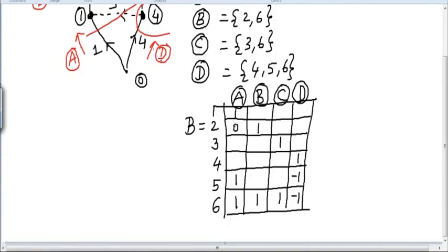Rest all the things are to be filled by 0. So in this way, basic cut set incidence matrix also is calculated. After this, let us partition it, because unless and until we make a partition, we will not be able to prove the fourth identity, fourth bit that is to be proved, that is CB is equal to minus BL transpose.